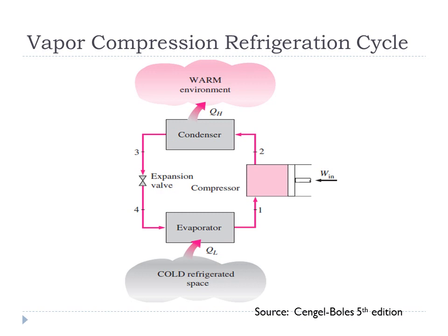After this point 3, the refrigerant in liquid phase would enter into the expansion valve, where with the help of expansion valve or capillary tube, the high pressure refrigerant is expanded up to very low pressure.